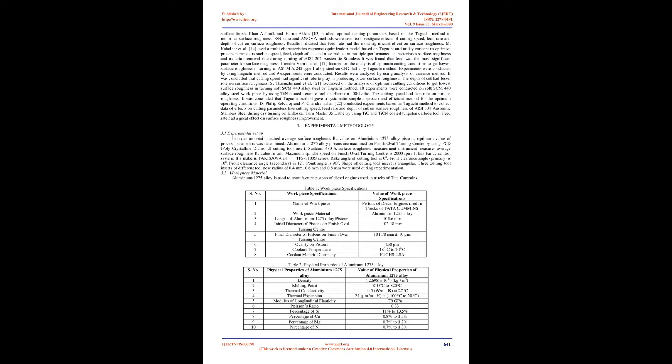This causes high manufacturing cost and low product quality. Hence there is a need to optimize the process parameters in a systematic way to achieve the responses by using experimental methods. Taguchi employed design of experiments, which is one of the most important and efficient tools of TQM, total quality management, for designing high-quality systems at reduced cost. Taguchi approach helps to reduce the large number of experimental trials when the number of process parameters increases.